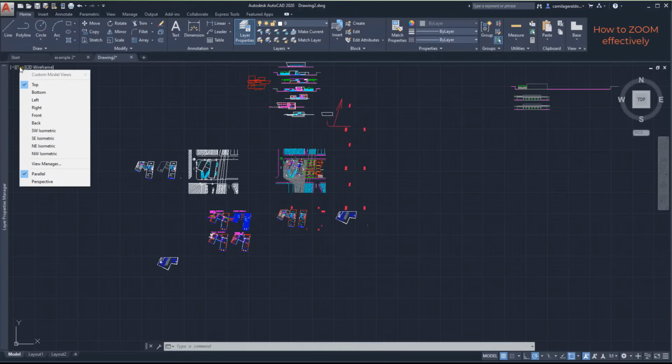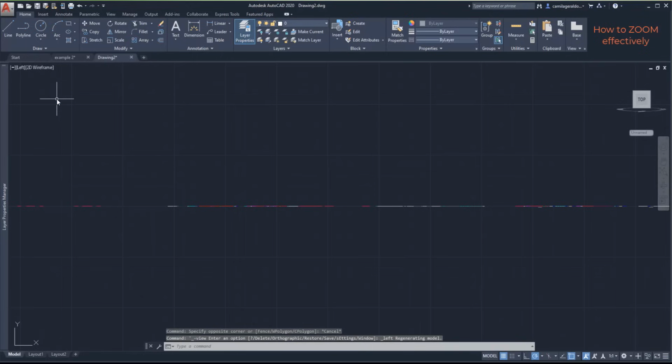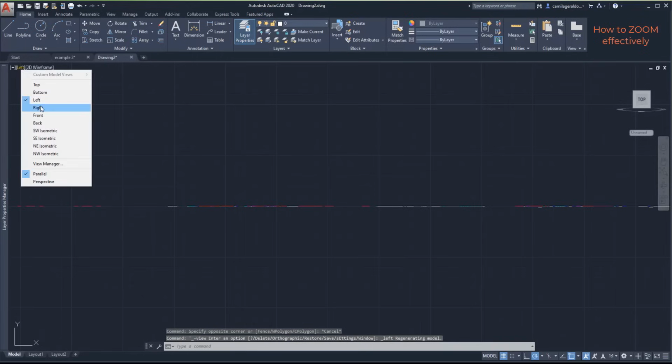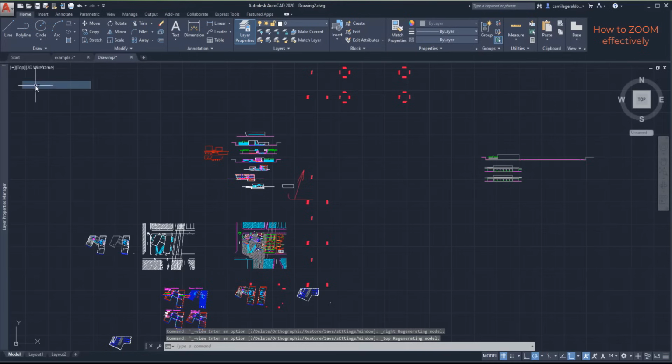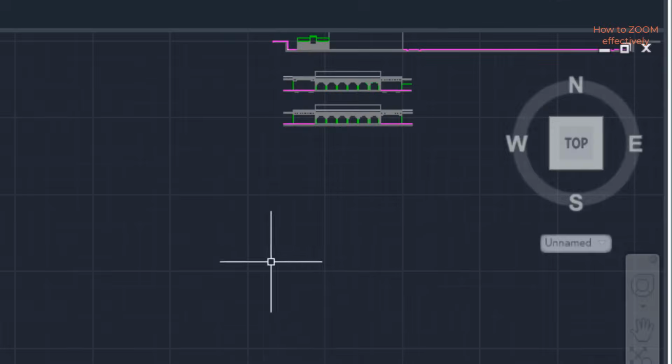However, the ones here are useful when I have 3D drawings. Look that I can't see anything interesting when I switch to the left or right views. This is because everything in this project is 2-dimensional and was created in the top plane. On the view cube, you can understand a bit better the location of the views by default, especially when you click in a corner to switch to an isometric view.